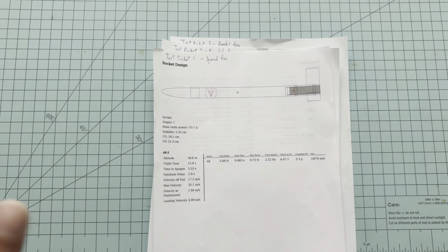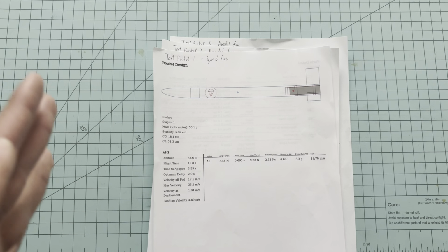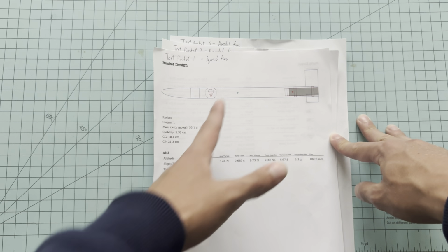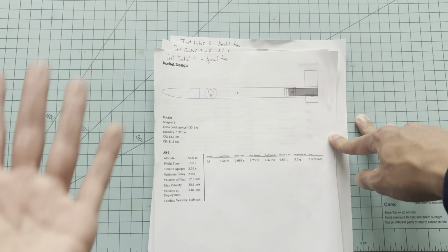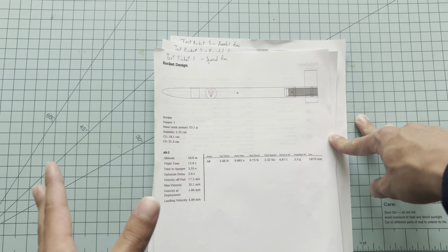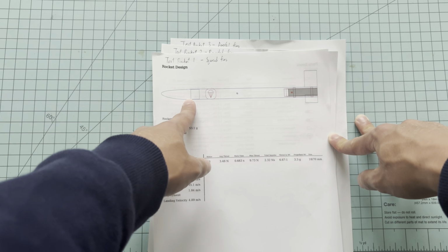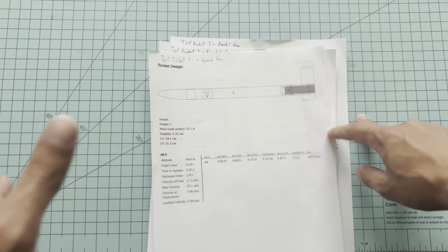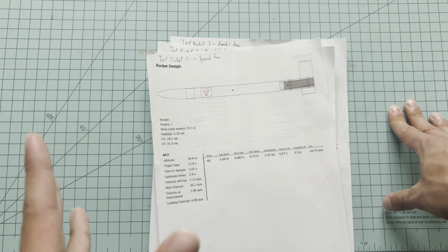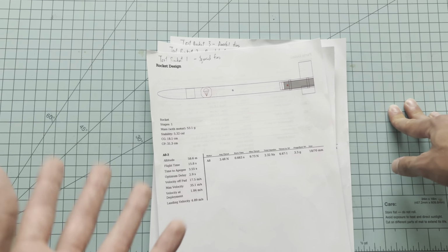Now, one thing I will note: I'm planning on using a 3D printed nose cone, which I already have made up in CAD. OpenRocket has a bunch of presets with data on what body tube you might be using and so forth, but they don't even have a material for PLA 3D prints. The good news is you can just make a nose cone element and do a mass override. You just go into the slicer of your 3D printer, see how much your nose cone will weigh, and do a mass override there.